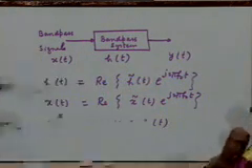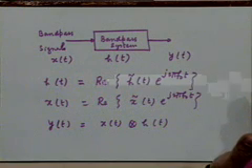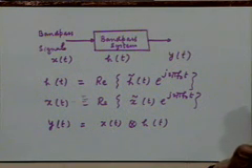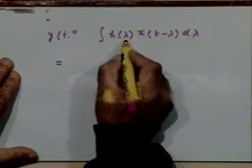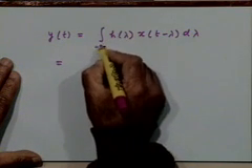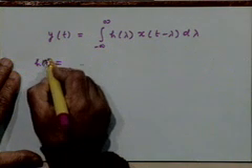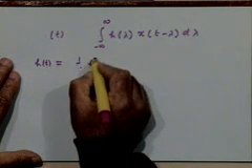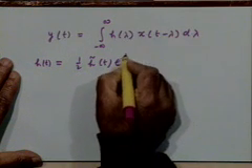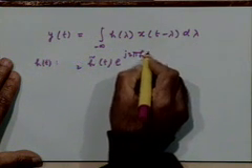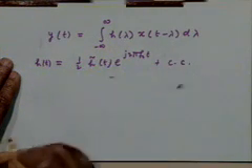The real part of any complex number is the sum of the number and its complex conjugate divided by 2, right? So I could represent h of lambda here. Lambda of course is a dummy variable ranging from minus infinity to infinity. I could write h of t as half of h tilde t e to the power j 2 pi f naught t plus its complex conjugate, right?